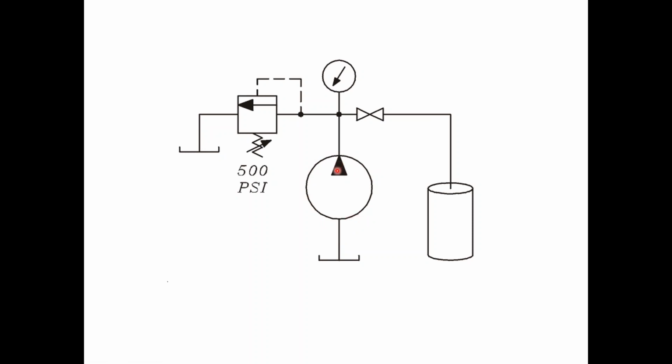You see an arrow that indicates an output. Notice that the arrow is filled in. That indicates we're dealing with a liquid. If this was just the outline of an arrowhead, then that would be a symbol for an air compressor. Right? But we're dealing with a liquid, so this is a hydraulic pump. Now, all the pump really does is take hydraulic fluid from one place and put it somewhere else. That's all it really does.